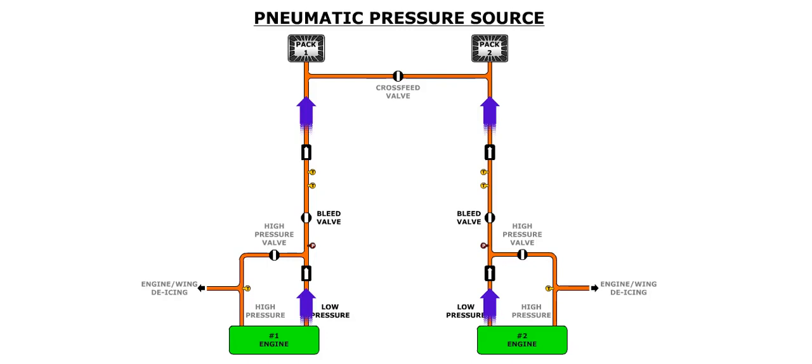Pneumatic air is produced by each engine. This air is tapped from either the high-pressure (HP) stage or low-pressure (LP) stage of the engine, and flows through the bleed air valve. Therefore, the bleed air valve must be open in order for an air conditioning pack to function.